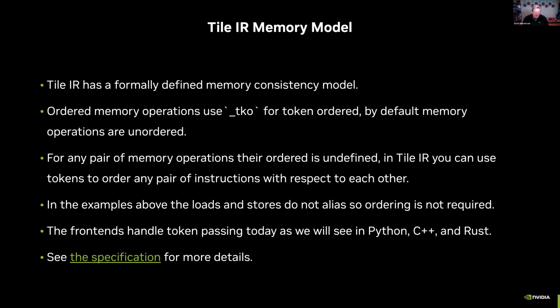So tile IR takes the assumption that memory operations can be unordered under most use cases, but they expose a capability of ordering them using these TKO operations for token ordered. Like I said, by default, memory operations are unordered, but if we absolutely need them to be, then we can do these TKO operations.